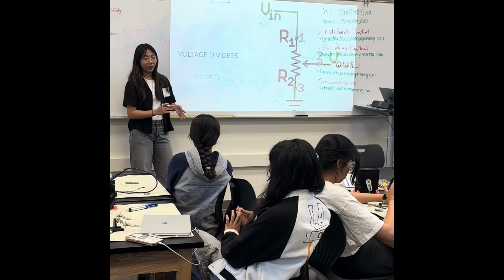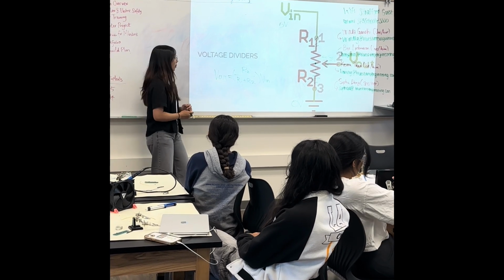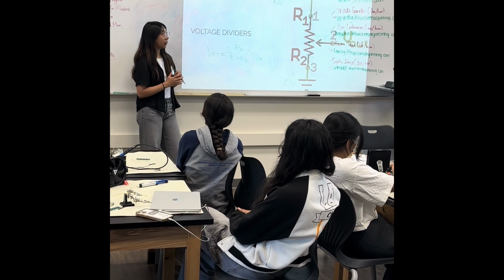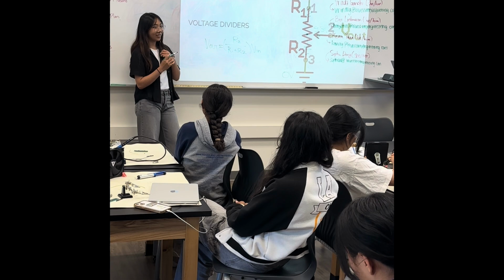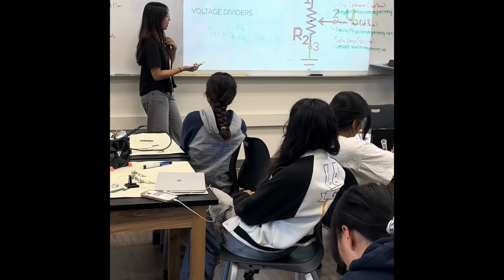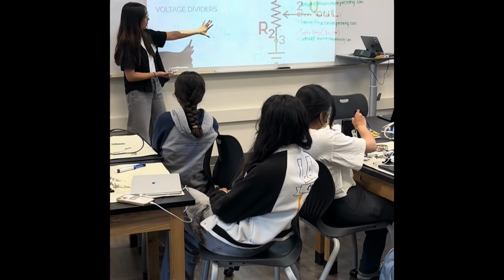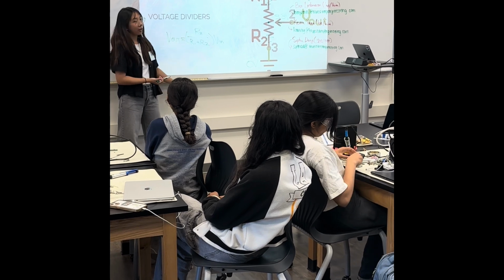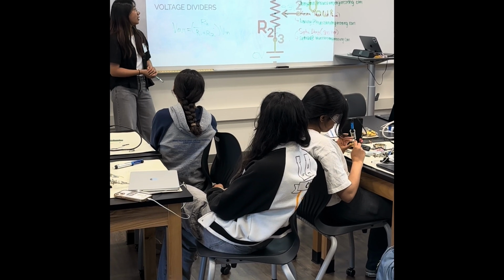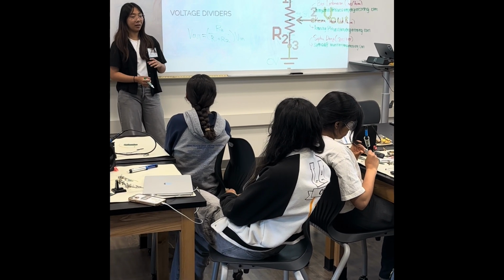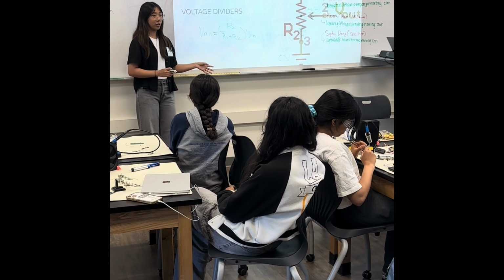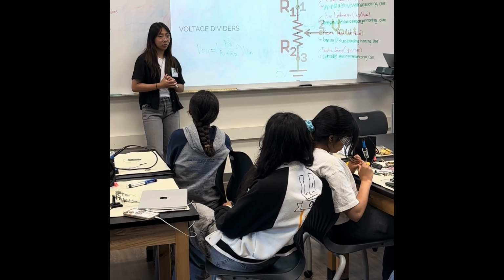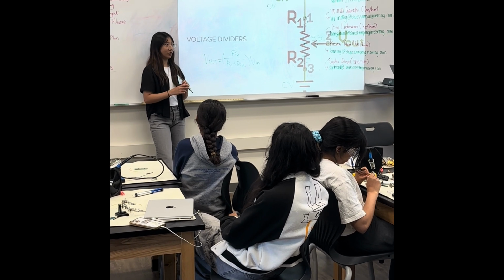With 5 volts and 3.3 volts, we're pretty lucky because 3.3 is almost exactly 2/3 times 5. That means that for the ratio of our two resistors, we just need a 2-to-1 ratio. So the actual values can be anything you pick as long as they're in a 1-to-2 ratio. However, we don't want to pick something too small. Say you pick 1 ohm and 2 ohms.